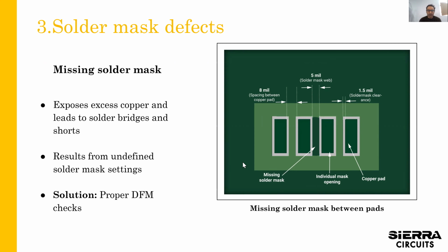So the purpose of solder mask is to cover the copper, so the copper is not exposed and doesn't oxidize. And second, to provide dams for the solder paste in assembly so that solder bridging doesn't occur. So you want to have a solder mask dam to help with the assembly part of the process.